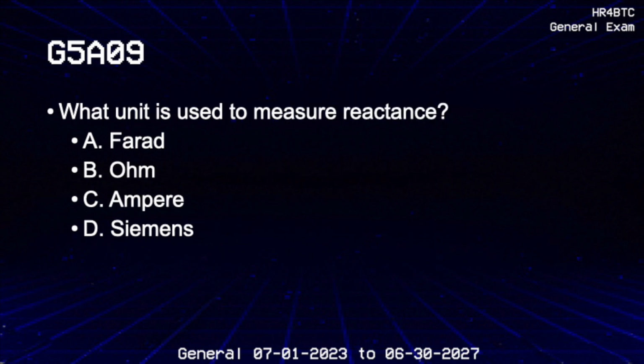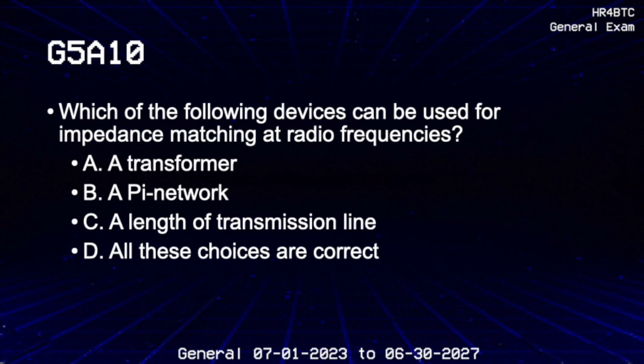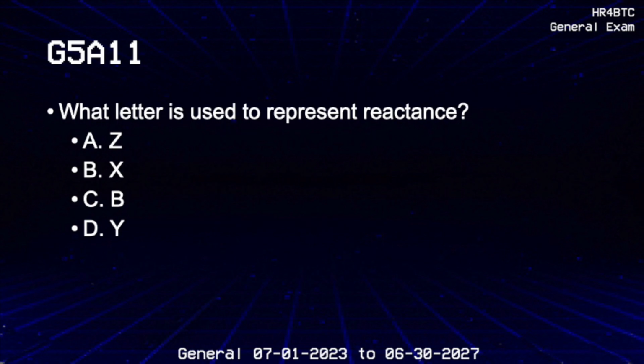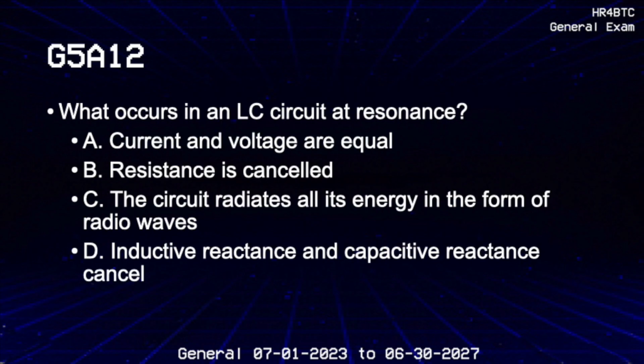What unit is used to measure reactance? Ohm. Which of the following devices can be used for impedance matching at radio frequencies? All these choices are correct. What letter is used to represent reactance? X. What occurs in an LC circuit at resonance? Inductive reactance and capacitive reactance cancel.